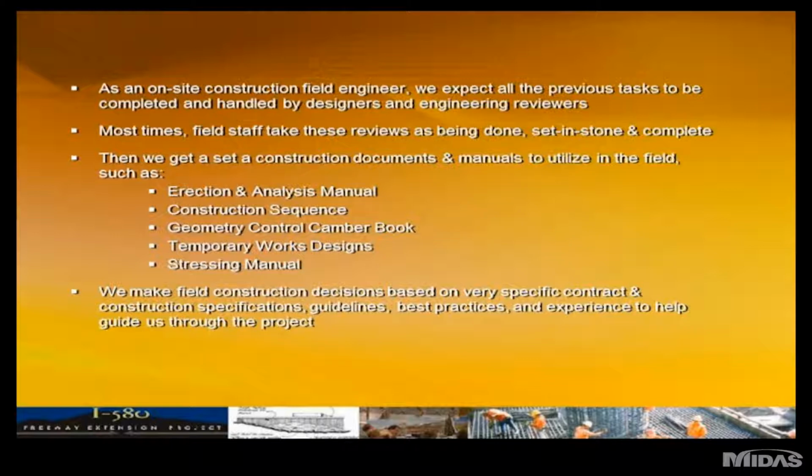So we get a set of documents and manuals that utilize the erection analysis, the construction sequencing, geometry control, cambering book, temporary works design, and stressing manual. We'll make field construction decisions based on very specific contractual specifications and guidelines, best practices, and our experience to help guide us through the project from start to finish.